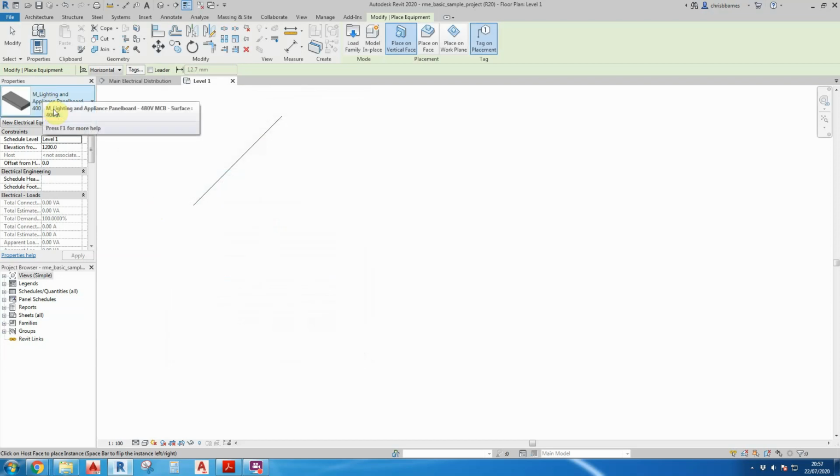If we want the board to be at different heights in different locations, then we would change the instance properties, which will only affect that particular item in that one place, not the remaining 4 other items in this example.